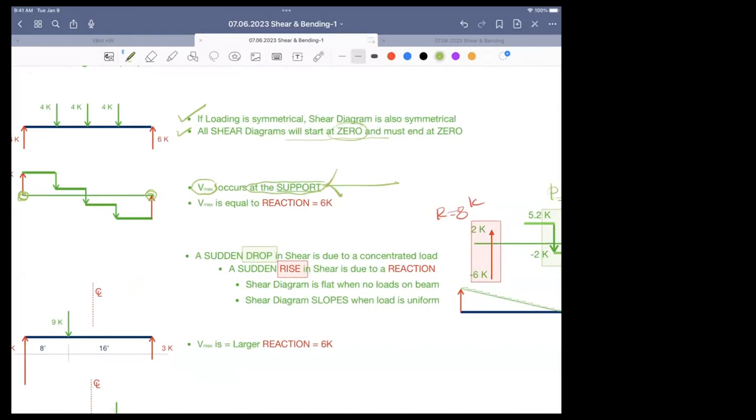Please, this is extremely important. That's where the maximum shear is. That's where I need all the bolts. That's where I cannot cut a hole to let a pipe through or a duct. You cannot touch maximum shear. Why? Because you're taking out area. Shear has to do with how many square inches. You cannot take out square inches to let a member through if the shear is high. If the shear is low, go for it.